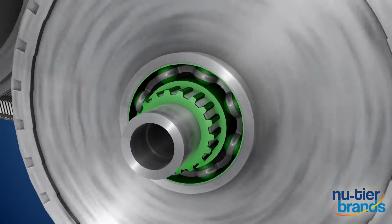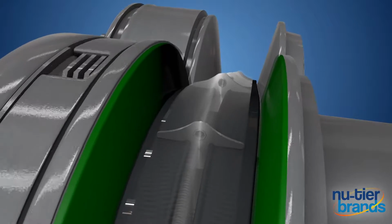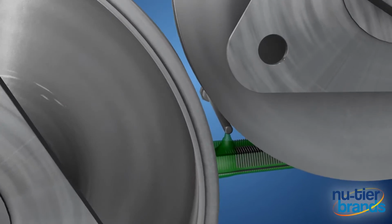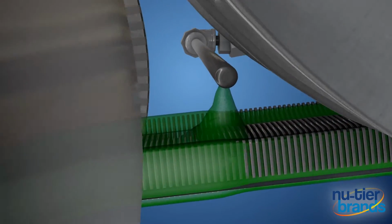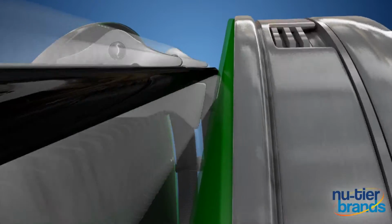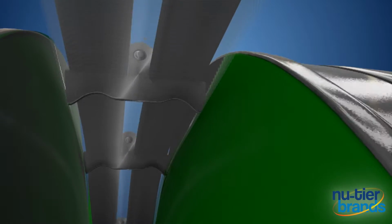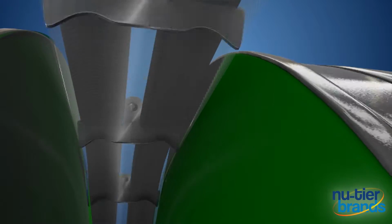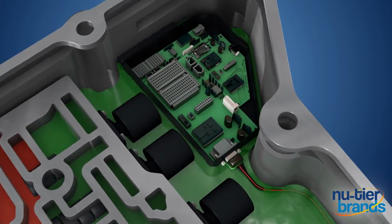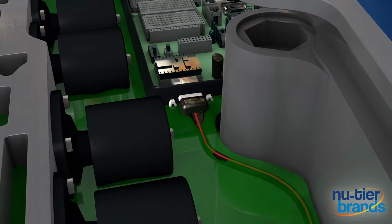And while the fluid reduces friction in the pumps, gears, and bearings, it actually increases friction between the push belt and the pulleys. The CVTF has to dissipate heat away from metal components and protect them from wear and corrosion due to high temperatures. It must be extremely tough and durable, since the prolonged metal-to-metal contact tends to break down the fluid quickly. Finally, CVTF has to be compatible with all the electronics and protect against unwanted conductivity between electronic parts.